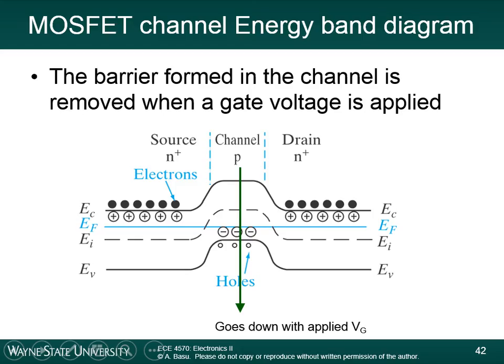This half of the diagram should look quite familiar because you've drawn p-n junctions before. And this is really no different. First you drew the p-type material, you drew the EC, EI, EF, and EV, and then you did the same for the n-type material, and then you bent the bands in order to get these continuous energy band structures. And this gave you the energy band diagram for a typical p-n junction. All we're doing right now is adding this part to it, the part on the left, because we have another n region over here.